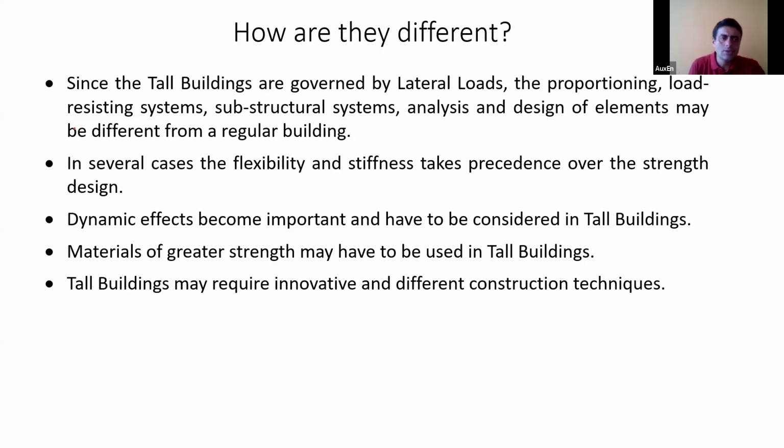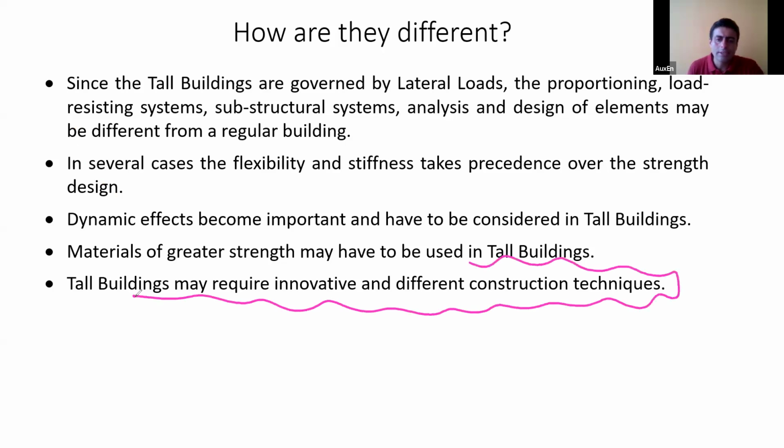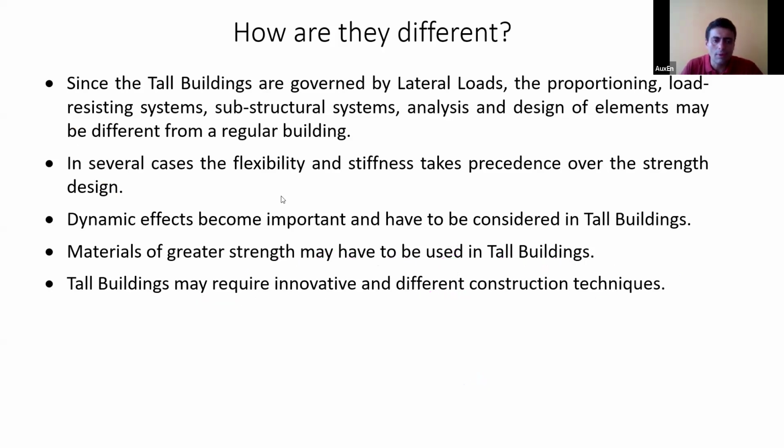And in tall buildings, you may have to think about some innovative and different construction techniques. For example, you may have to think about slip form techniques. You may have to come up with slip forming solutions where you do continuous concreting, continuous casting to save on time. You may have to come up with different systems which save your time and help in faster construction. So in tall buildings, these issues may also need to be thought about.